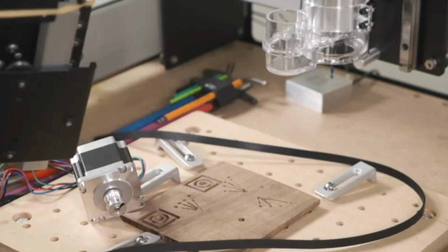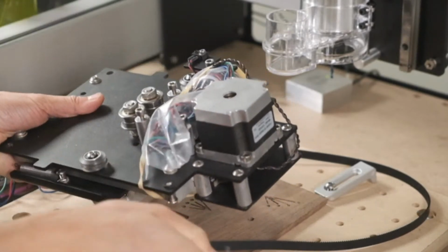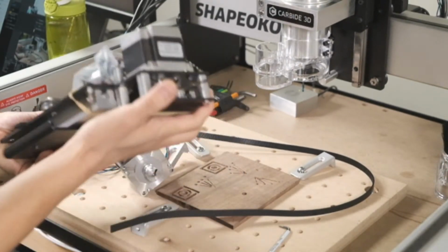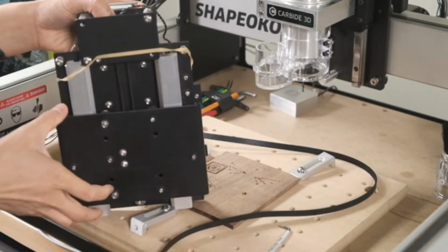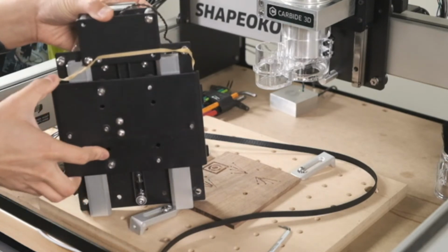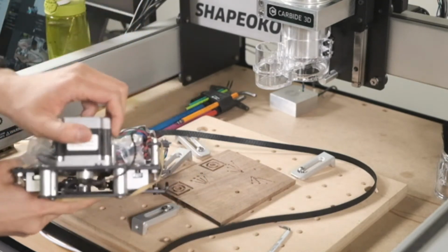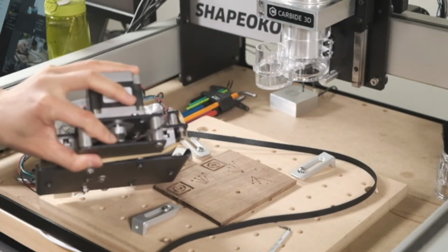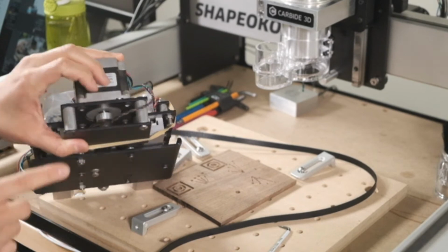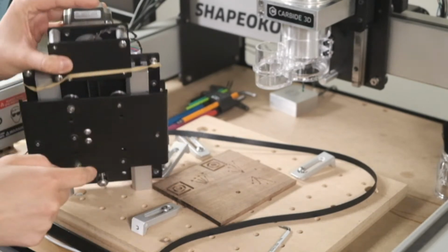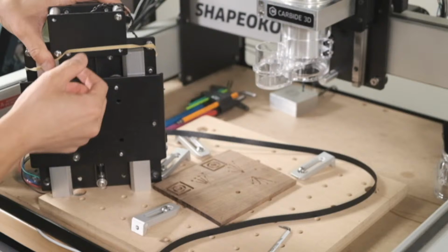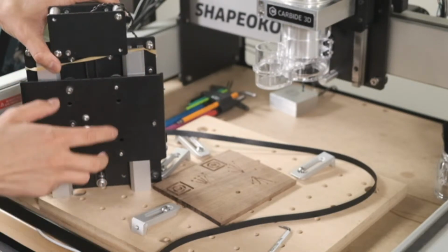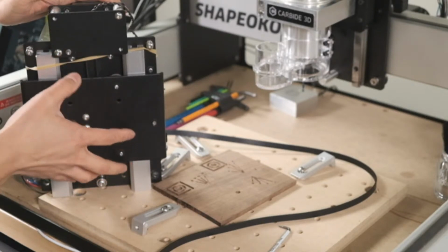So on the belt-driven axis, let me zoom out a little bit. This is a little too close. People will sometimes have the issue where this doesn't move as expected or it slips. That pulley for the stepper motor can sometimes be a little loose. So I would check there first if you're having any motion issues where either the commanded motion isn't being replicated or there's a little bit of slipping.